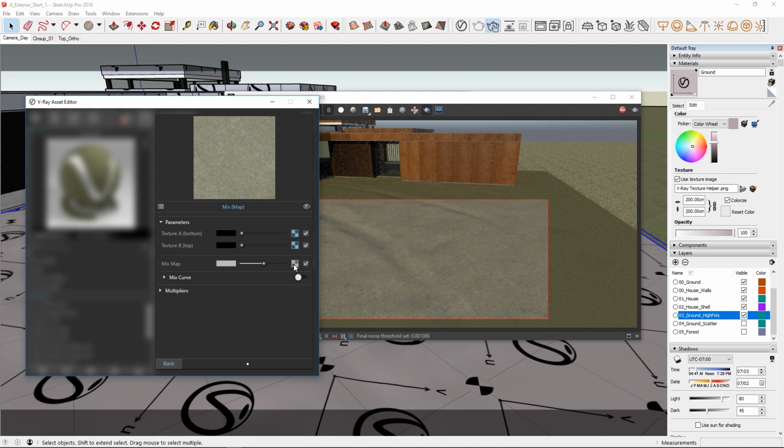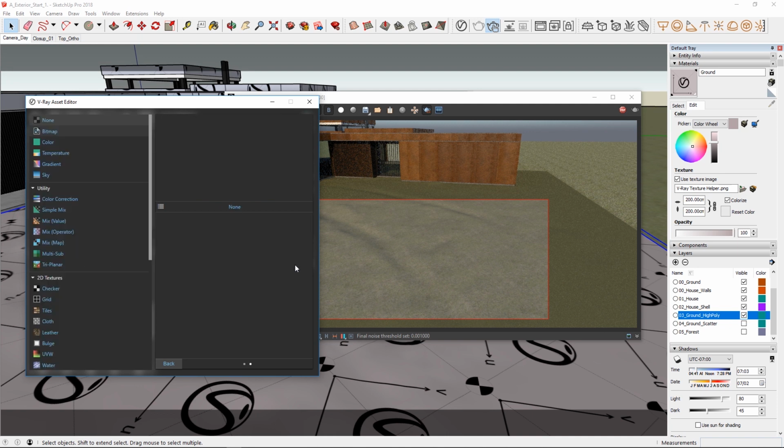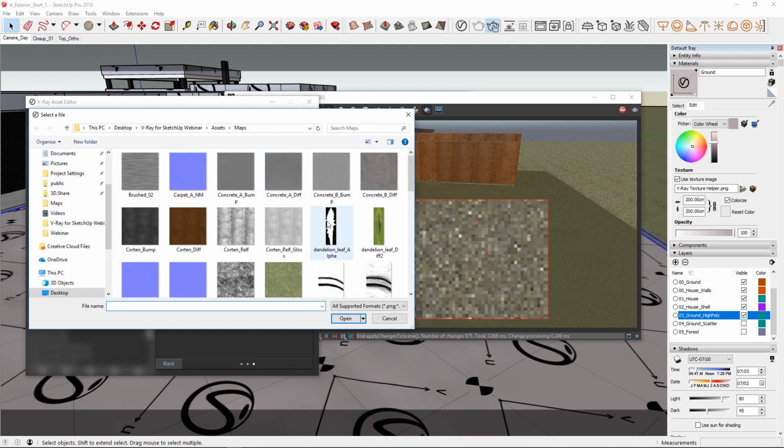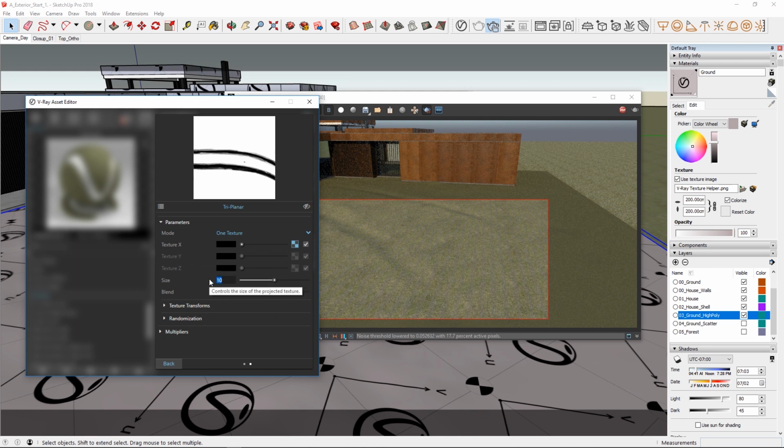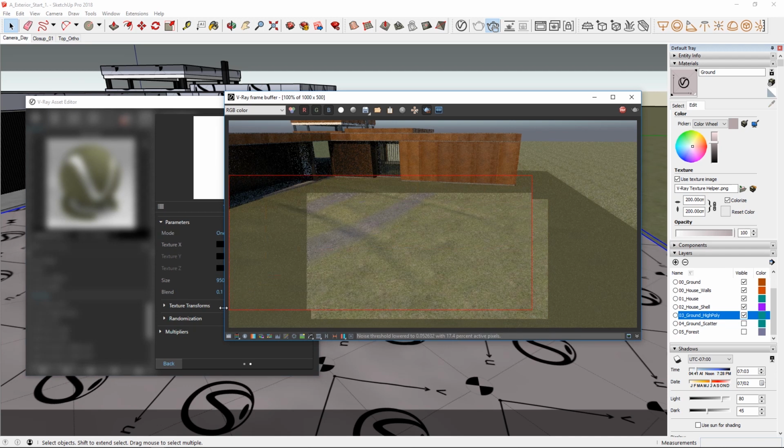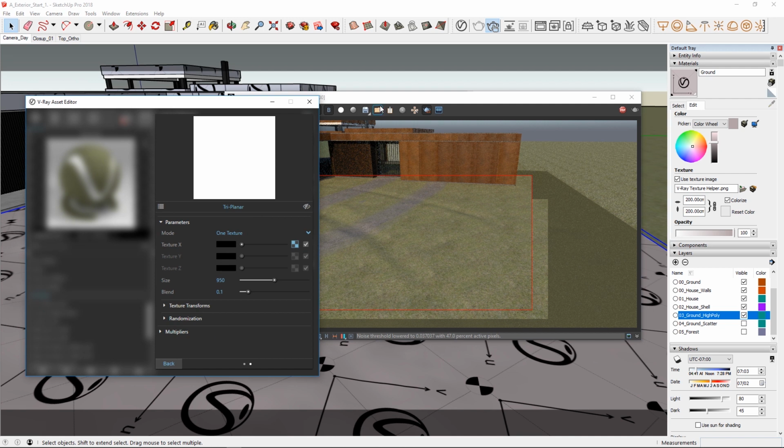To control the mask's scale and position separately from my current material, I'll use a tree planar map and load the mask. The tree planar texture works by projecting one or more textures along the object's space axis depending on the surface normal of the shaded object. I'll use only one image for all axes and start with adjusting the scale. I will probably need a higher value, but it depends on the size of the mask you have prepared. You can already see how it works.